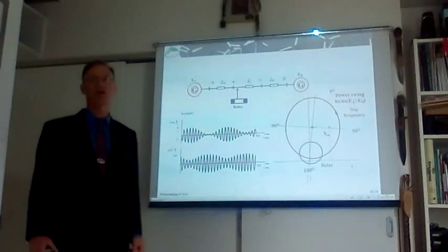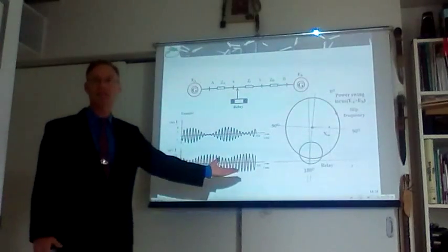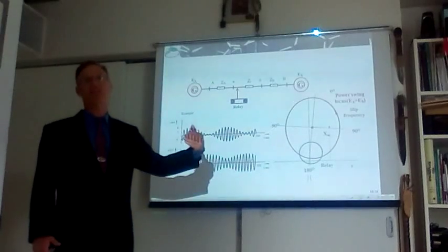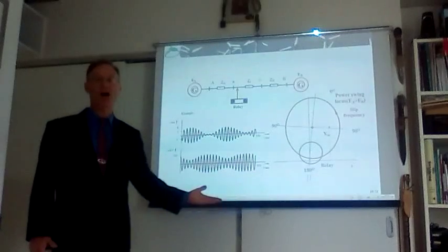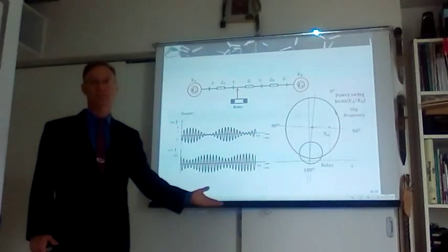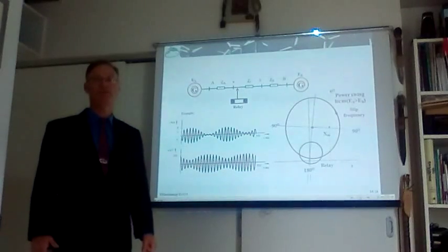And that is exactly the duty of a distance relay. Measuring the impedance of the line and deciding based on that if we have to trip or not. And this is the summary of distance protection relays.